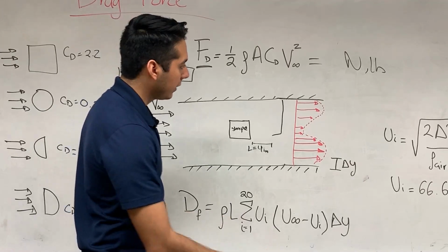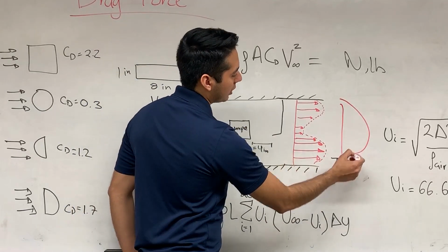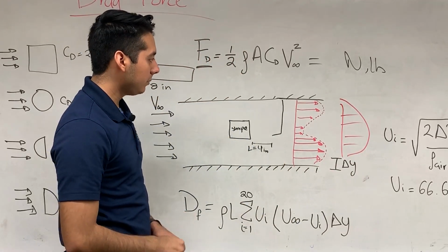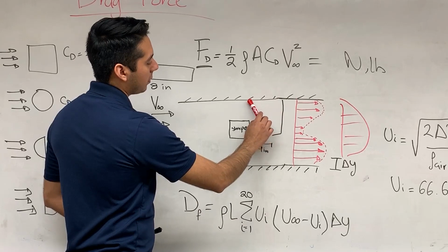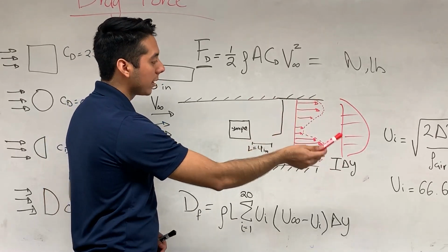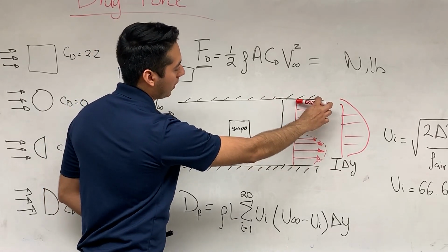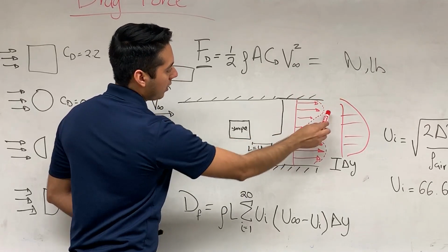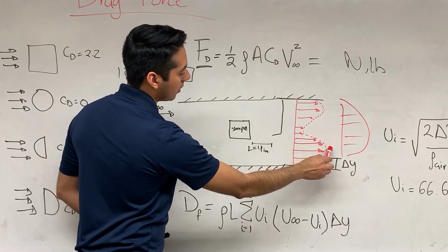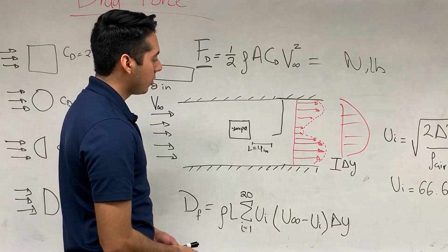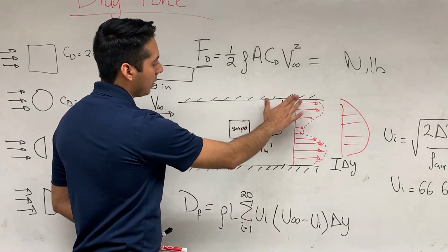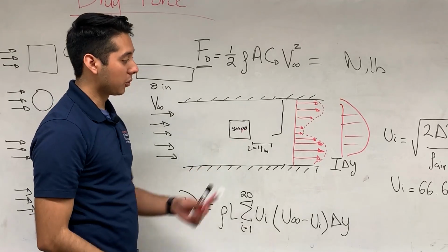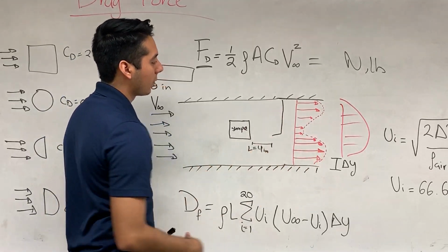It looks really different from what we were measuring in other labs when this was our velocity profile. You can see it starts at the very edges. It's kind of low because of the friction, but as we move away from the edges, it increases a little bit in velocity. But once we're closer to the shape, you can see we get this decrease and then it goes back up. So something you can notice is that the velocity profile changes as you get close to the middle. Most of the shapes will give you this kind of profile.